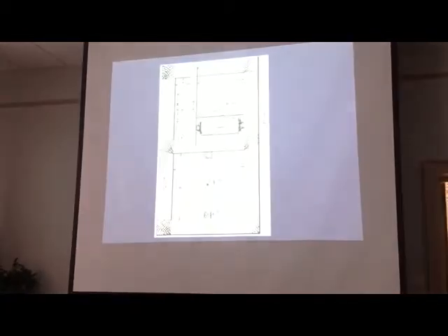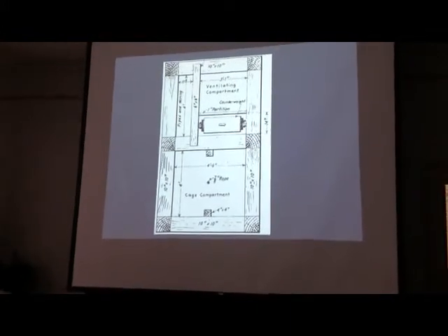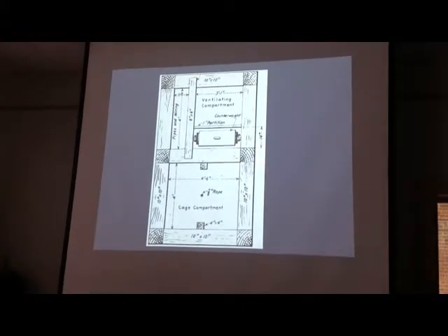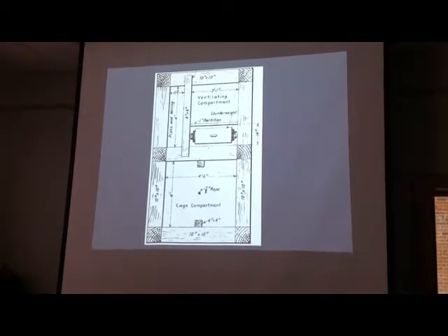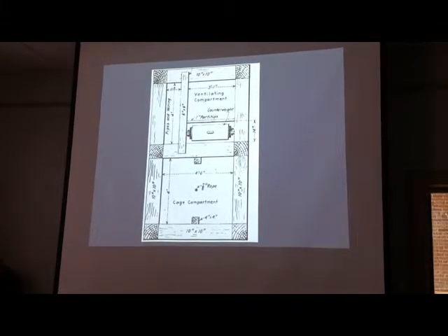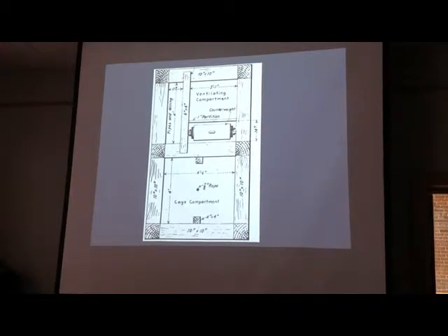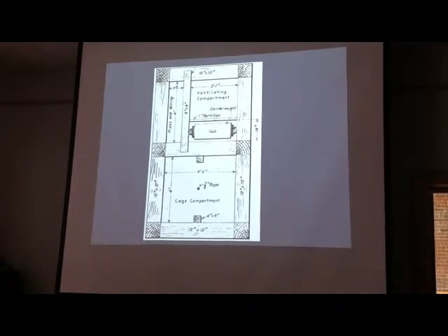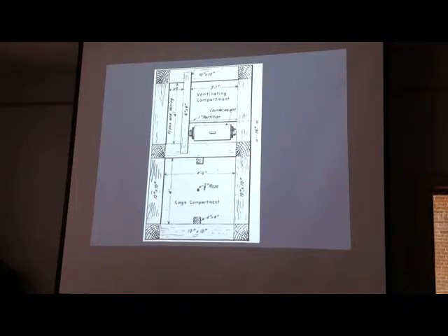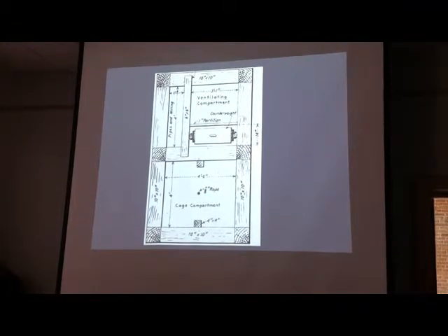They put 2 sets of ropes on it, put a counterbalance in the second compartment, and then with the concrete, they tried it out. You just cut down the ventilation compartment, a very small amount. And what they did was, by basically using a single drum hoist, they were able to equalize the power at 102 horsepower both ways. And by putting a flange down the middle of the drum, they increased the diameter of one side by 6 inches, and used a sheave wheel 6 inches smaller on the ventilation compartment side of the head frame.